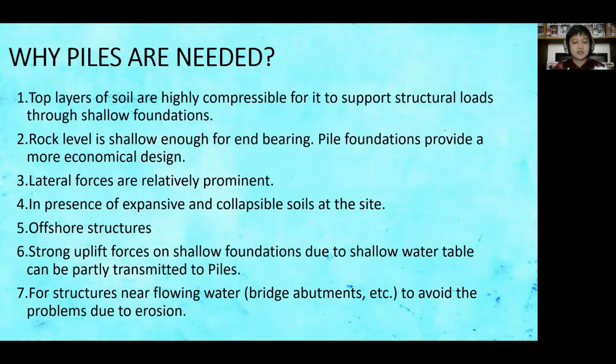Sixth, strong uplift forces on shallow foundations due to a shallow water table can be partly transmitted to piles. Uplift forces may push the shallow foundations or footing, thus piles are built and injected at deeper strata.